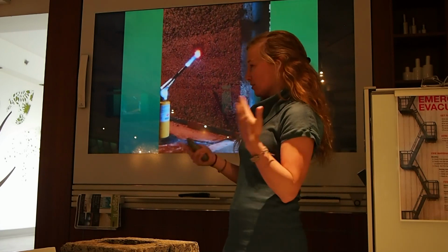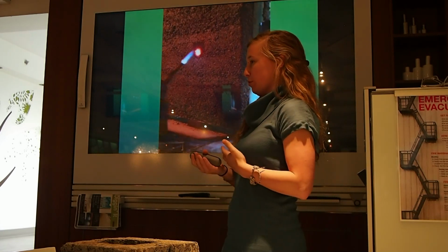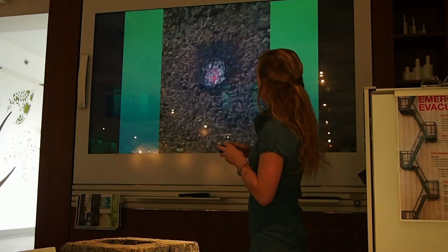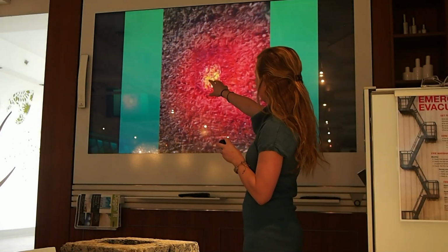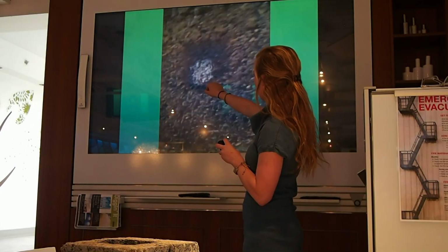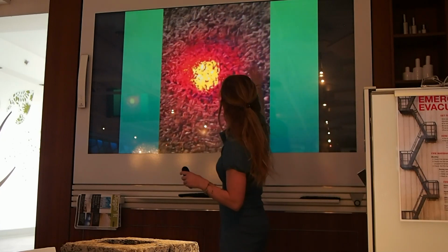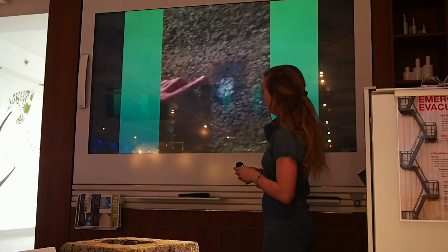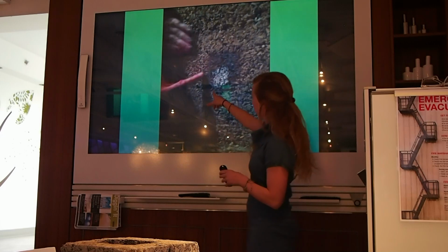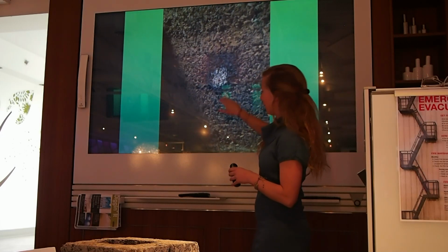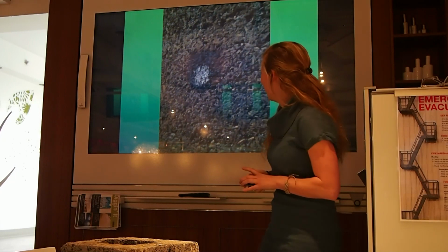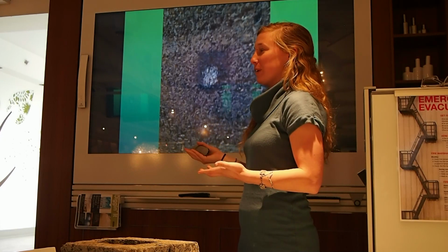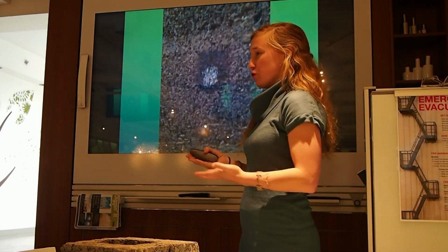And so besides those qualities, it minimizes thermal bridging. It has breathability because it's a natural material. And you can see this guy's about to put his hand on it, unless it already happened. I think it did. So where he's touching right now is all cold. And it's a little warm where his pointer finger is, and then right on the black surface is where it's hot. And that's after 3.5 minutes of burning of a straight torch.